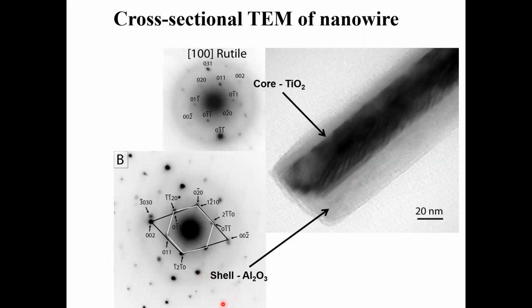Titanium 6-4: 6 for aluminum, and 4 for vanadium alloying elements. In the Ti6-4, when we cross-section and do a TEM on one of the fibers, you can see there is a core, and the electron diffraction confirms the core to be rutile TiO2. And there is a clad layer, a shell layer, you can see that clearly, and the electron diffraction matches aluminum oxide.